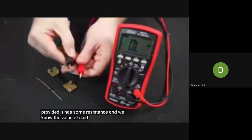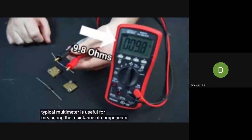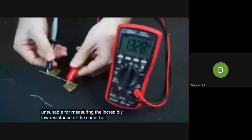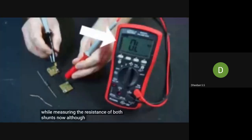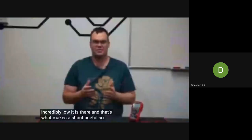A typical multimeter is useful for measuring the resistance of components down to say 1 ohm. However, they are unsuitable for measuring the incredibly low resistance of a shunt. You can see my meter reads all zeros while measuring the resistance of both shunts. Now, although the resistance is incredibly low, it is there, and that's what makes a shunt useful. So basically a shunt is a low value resistor.